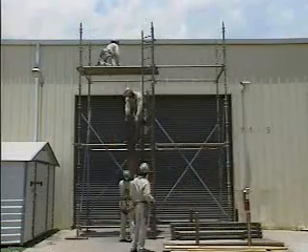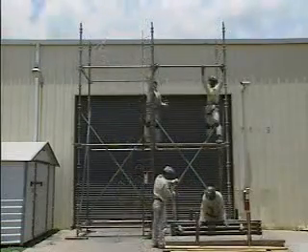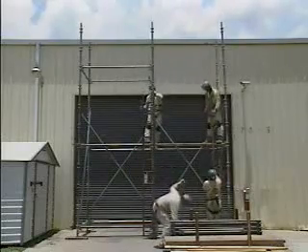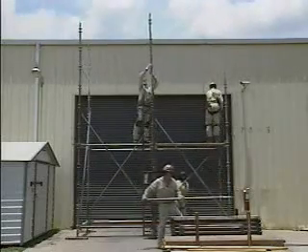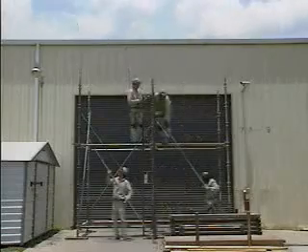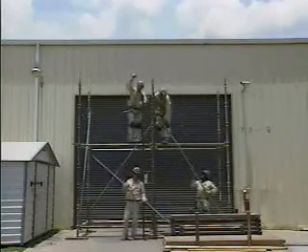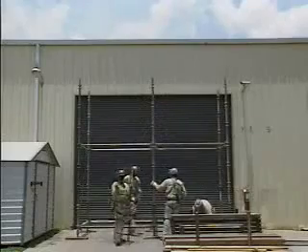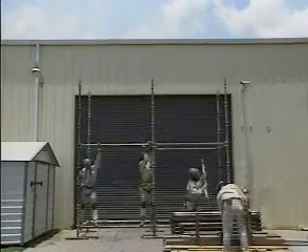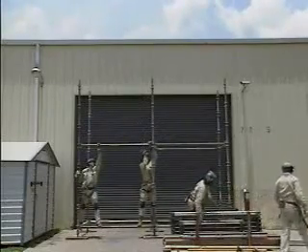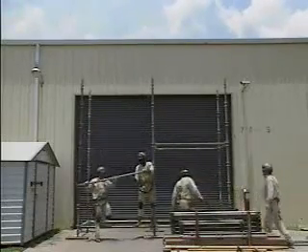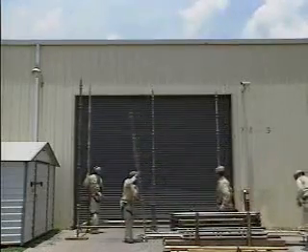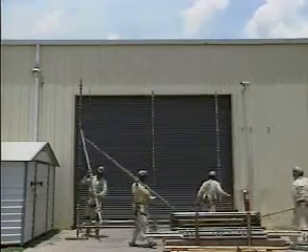The scaffold flooring is removed next. Then the horizontal members that served as the floor supports are removed, along with the upper vertical legs. Next, the diagonal braces are removed from the vertical legs, and the ladder is taken off. The horizontal members that were connected to the midpoint of the first set of vertical legs are then taken down, and the vertical legs are lifted off of the starter collars.